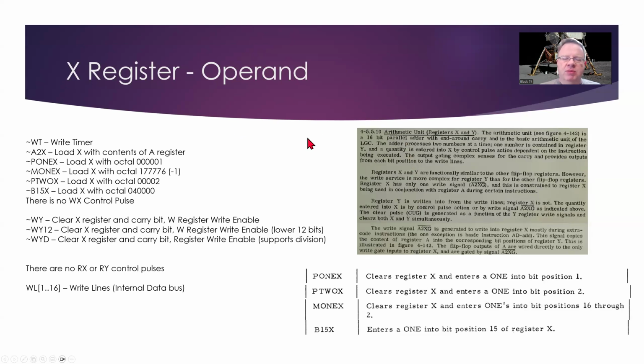So we'll talk about that as we go into the input commands. I'm going to break the X register into a couple of episodes. Today we're going to talk about how data gets into the X register and the various control pulses that operate that. In the next episode, we'll talk about how the adder works, because at least in how I'm implementing it, the adder is going to be closely tied to the X register. And then the outputs of the adder have some additional complexity.